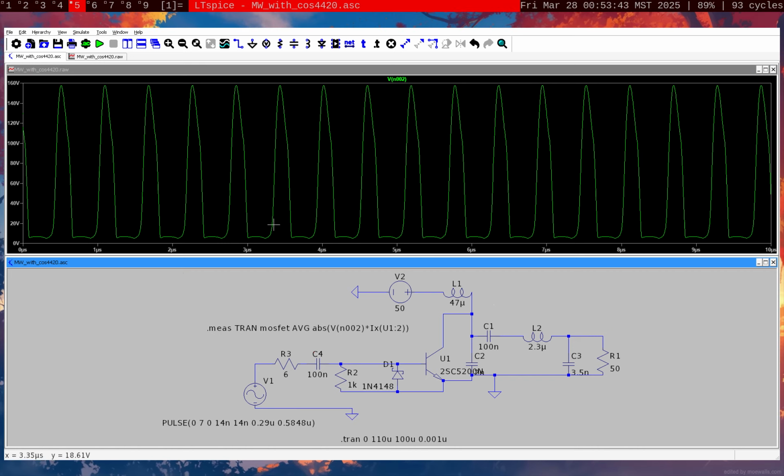But I think the rise and fall time, the drive level, and this capacitor here for the Class E amplifier, they're kind of intertwined with each other. So yeah, you don't want to overdrive the amplifier. You don't want to switch it too fast, actually, because that would cause problems, like I will show you soon here. So yeah, now we can close this